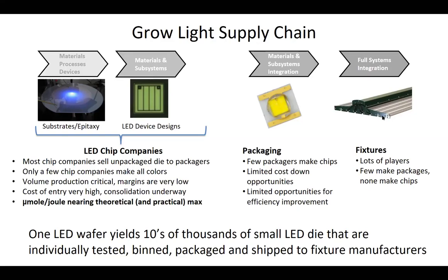The fixture, anybody's guess, depends on how well it's made. And it really depends on how well you can solder the LEDs onto the board, how well you solder all the wires together, how well the driver is made. I would say that, at least from my experience in the solid state lighting world, where you buy an LED light bulb or an LED lighting fixture and you put it into your office or into your building or into your lamp, almost all the failures are related to a failure of a non-LED component, either a solder joint or a driver.